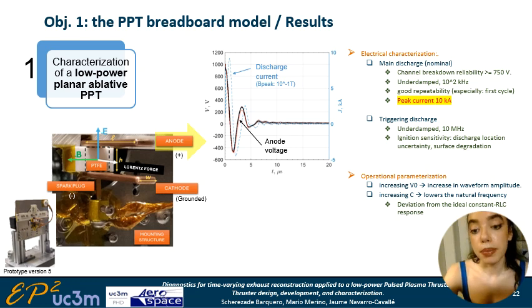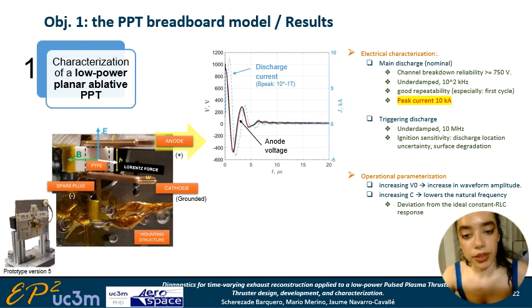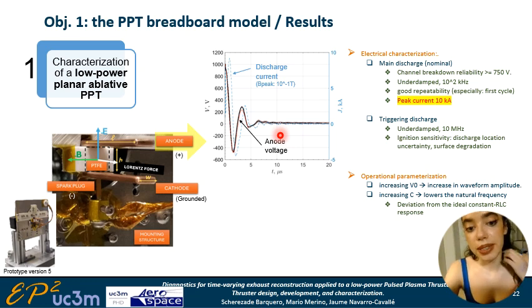To better understand the problem studied, let's just keep in mind about the thruster operation that the electrical discharge of the capacitors works in the underdamped regime for this capacitance regime in which we work, which is basically constrained by the size limitations of this operational range. The natural frequency of that is in the order of several hundreds of kilohertz, and also the discharge time is of several tens of microseconds, with the main part happening along the first few microseconds.